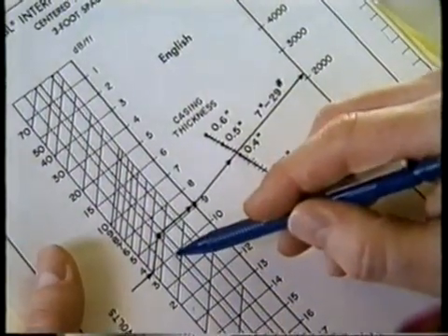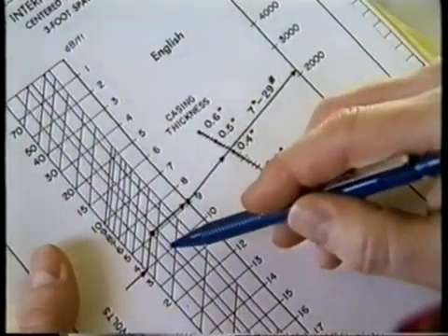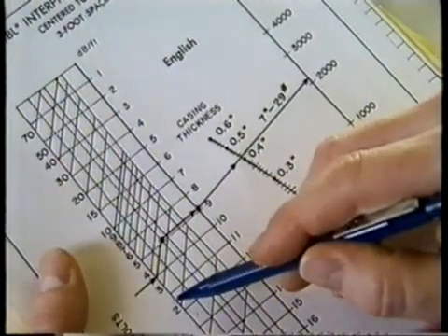The equation for the bond index is expressed in units of decibels per foot, while most amplitude curves are presented in millivolts or percent-free pipe. Most service companies have charts to convert from millivolts to decibels per foot, and vice versa. An example is given in your manual.